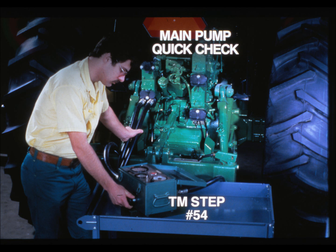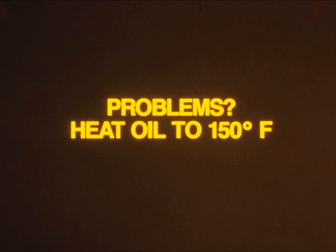If the oil flow is within specifications listed in the procedure, your diagnosis is complete. If you have gone through the entire procedure and still have not isolated your hydraulic problem, warm the oil to 150 degrees and repeat all the tests. It may take hotter, thinner oil to isolate the problem. In many tests, the procedure will give you different specifications for 150-degree oil.